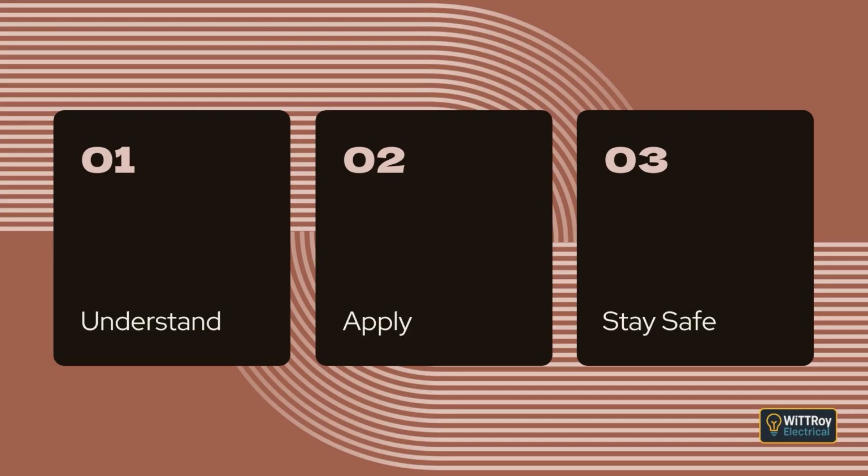This clause deals with arcing faults that happen inside a switchboard. An arcing fault is when electricity jumps through the air between conductors or metalwork, creating extremely high heat and pressure. These faults are dangerous, and heavy current switchboards must be designed to reduce the chance of an arc starting, and to reduce the damage if one does occur. A heavy current switchboard means the supply to the switchboard is 800 amps or more per phase.